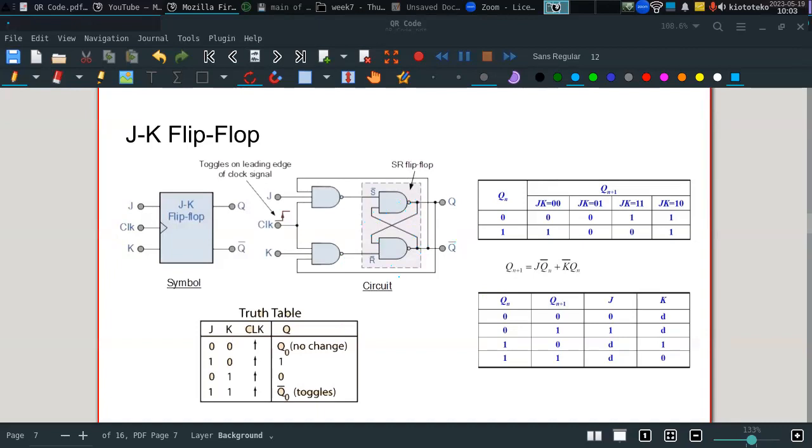Wait, didn't that start as a flip-flop? No, this is a JK flip-flop. Oh yeah, you see this? Why is it called a flip-flop? Because there's a clock signal that synchronizes all. Isn't that just an SR latch? Yeah, this is an SR latch, you see. So why does it say flip-flop? Because you have this other part. Adding those two other AND gates makes it a JK flip-flop.